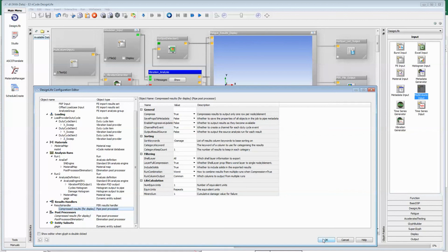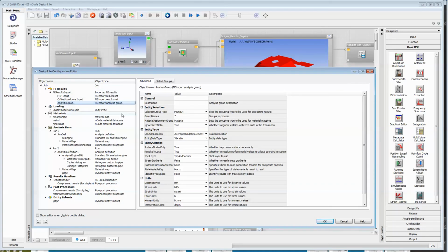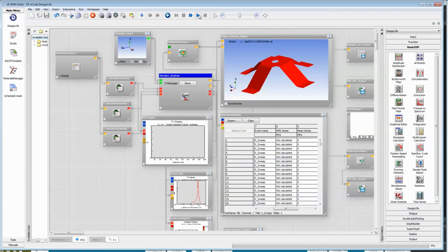Once this is done, the last setting is that we have to make sure the unit systems are correct. We have solved the harmonic analysis in Ansys Mechanical using the MPa unit system. So this has to be in MPa, tons and Newton meter. If you see this in some other unit, make sure you set this in MPa, tons, and so on. Having this set, I think we are through to run. We can run the model.